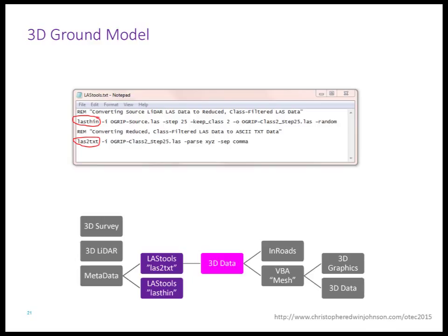And so this takes me to showing very simply a couple of command lines that are used for an open source tool called LAS tools. The first line of this code, as I've listed there, is filtering out and just going to give me exactly what I need. In this case, it's the ground. The next line reduces those points because it actually has a higher precision than I need for this intent.